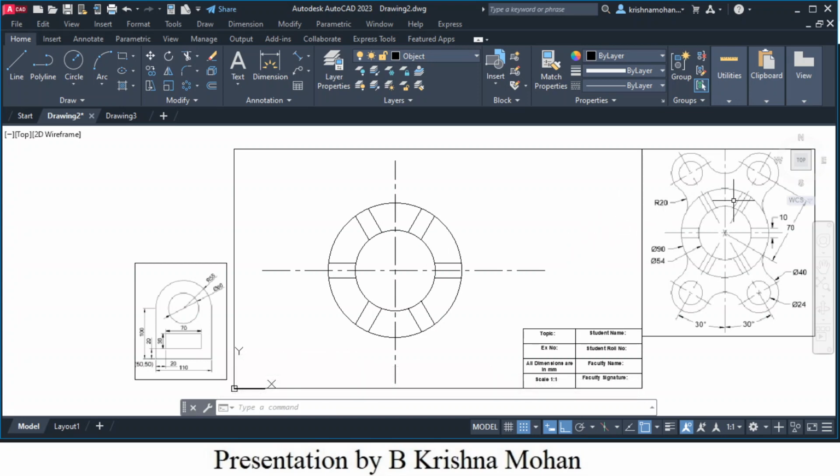So now my aim is to create. See, if you clearly observe the sketch, no, see, this entity and this entity are similar or symmetric about this line. Similarly, these two entities are symmetric about this line to produce the remaining entities. So these two are symmetric about this line. So instead of creating 4 different features, no, I will create one, and I will try to use mirror option to create the other entities.